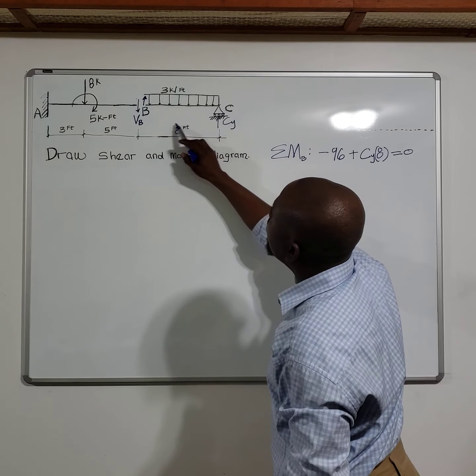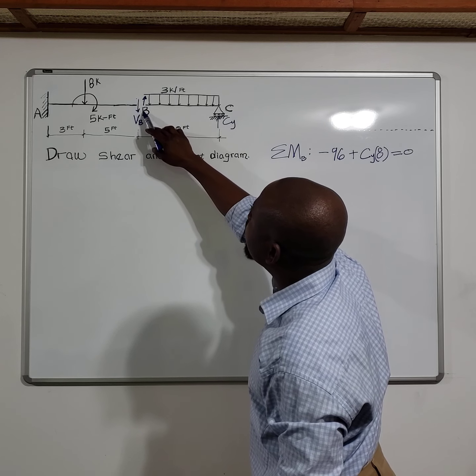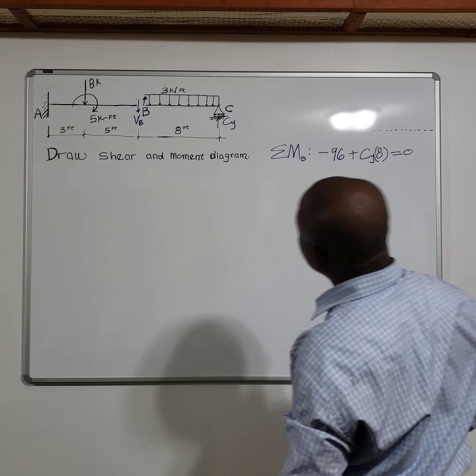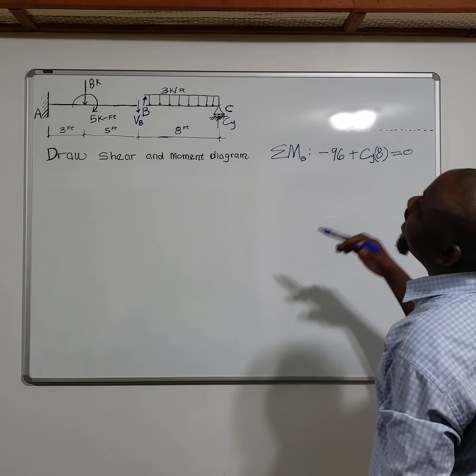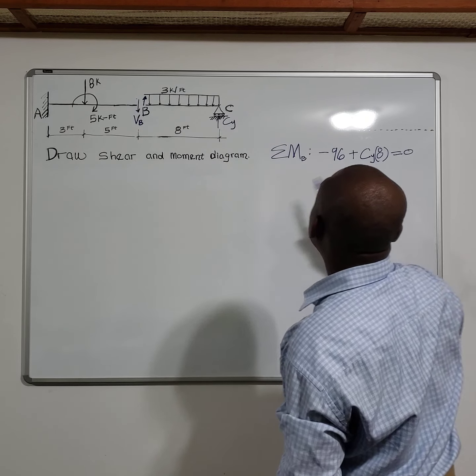There's no additional force along here. Your moment point is here, so it doesn't contribute to that moment in this case. And in particular, there's no moment at a hinge support. So this is what you have.